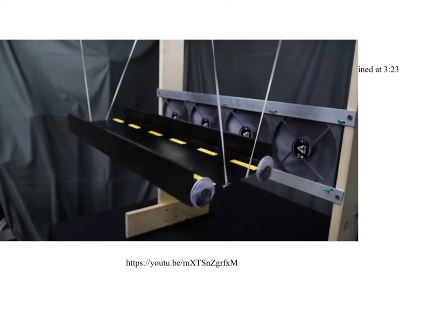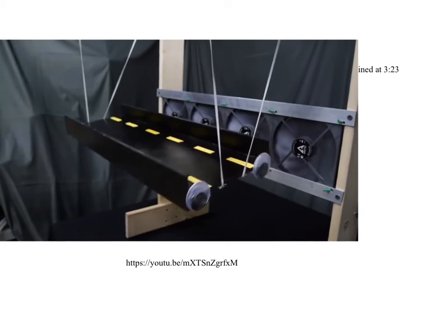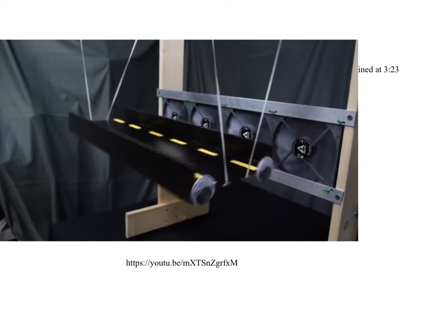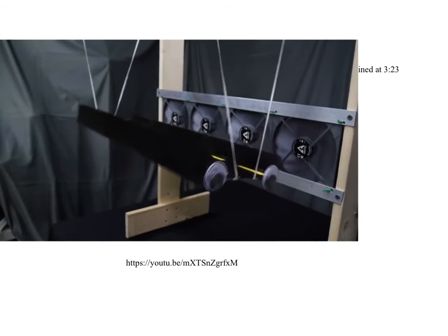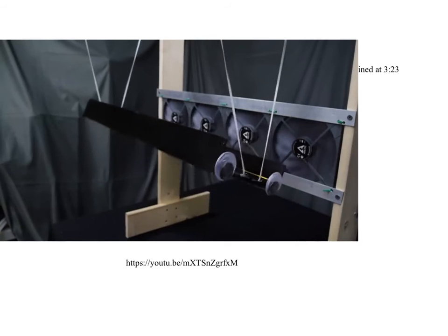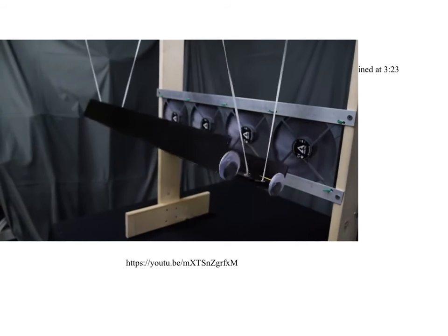It's the same reason that a strap or sheet of paper vibrates in the wind. It's a completely separate mechanism than resonance from vortex shedding because the periodic forces are self-induced from the naturally unstable aerodynamic shape of the bridge. This flutter eventually created too much stress in the suspension cables, and the bridge failed.